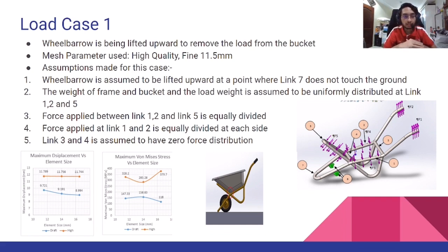The method that we use to choose this mesh parameter is by trial and error to find the minimum and the maximum mesh parameter that the SolidWorks can render. And after finding the minimum and maximum mesh parameter, we plot the output to see at which value the output converges to, so that it shows little variation between the output to make it more precise.